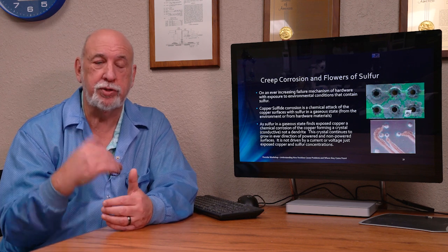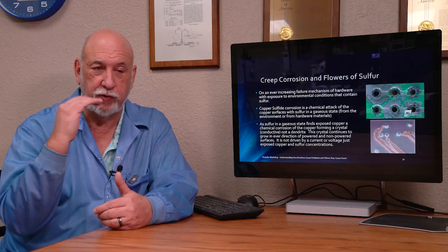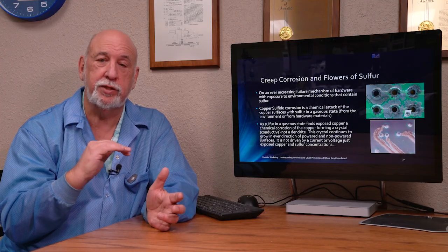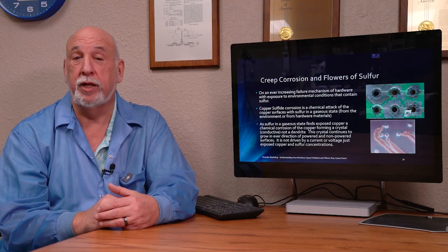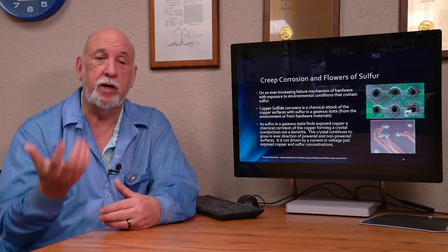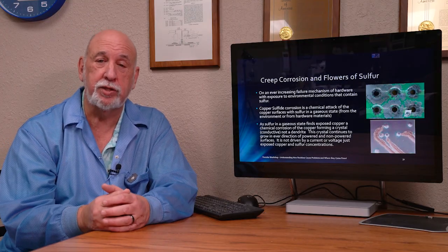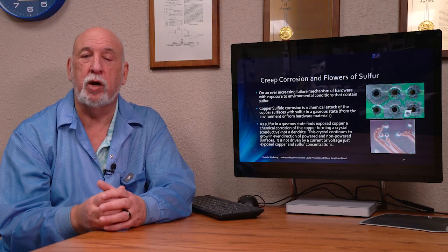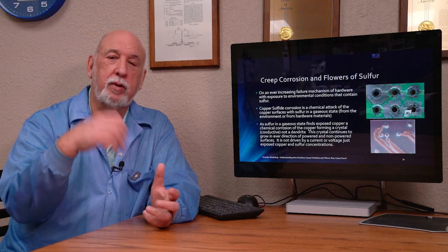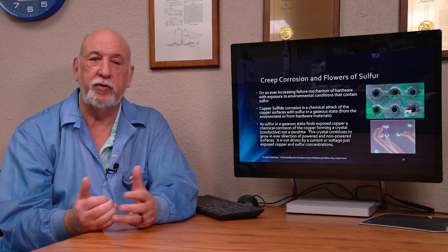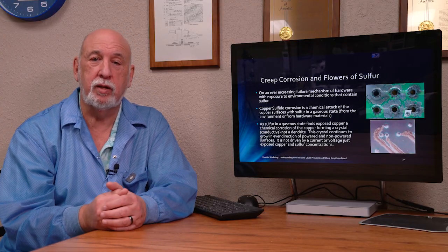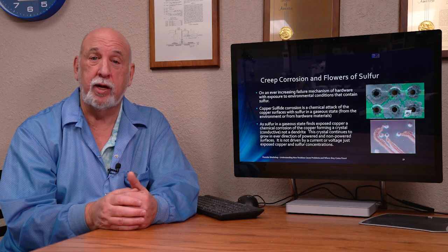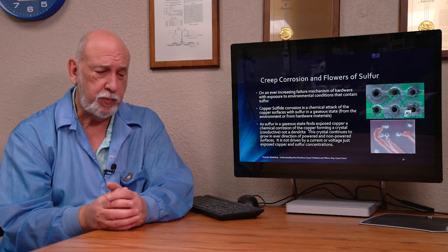We've measured, using LIBS analysis, different concentrations of sulfur inside the silicone, inside a lens, from a sealed system where they had sulfur-rich anti-vibration foam around the LED. It outgassed sulfur in a very short period of time, and then it caused the LED to fail miserably. And we were able to recreate that in some of our testing.